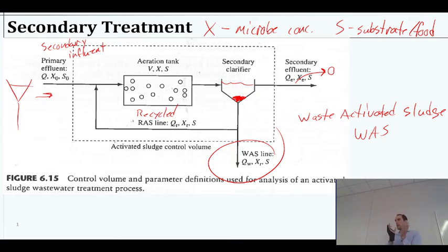You could then send it to kind of a compost process. If you get the right temperatures, it kind of helps with pathogen control. Then you can repurpose that as biosolids for land application, kind of fertilizer. So it's basically composting. We have some concerns of heavy metals in that, so we don't want to overload it. Otherwise, it's just going to go to a landfill.